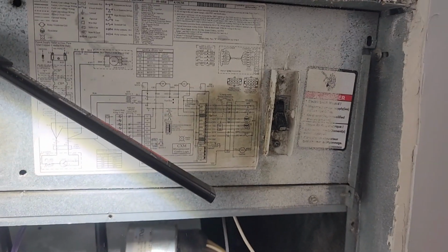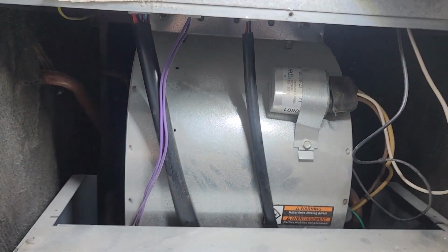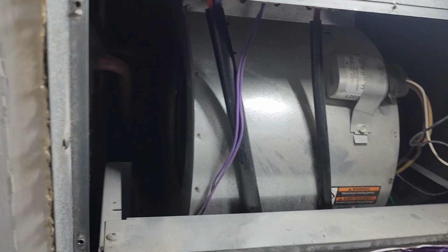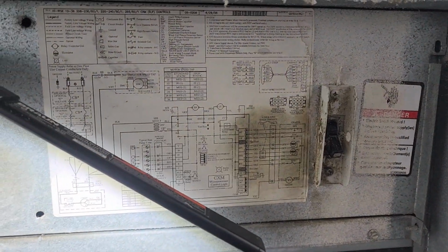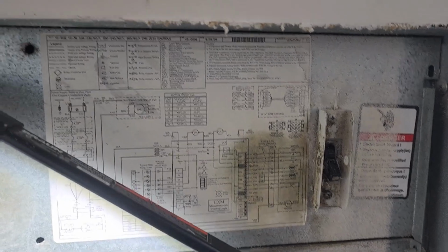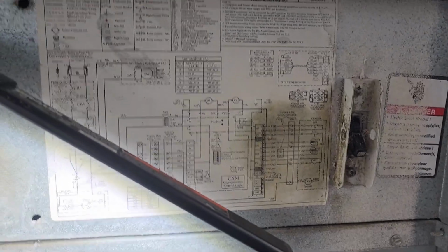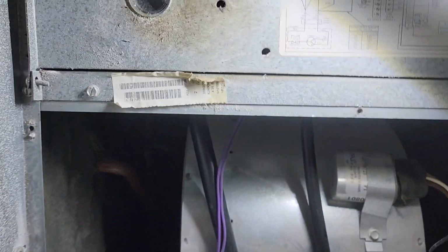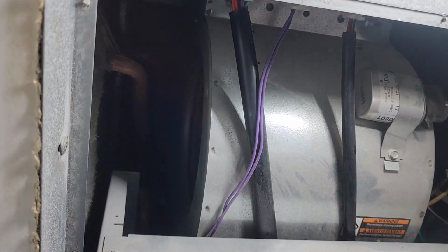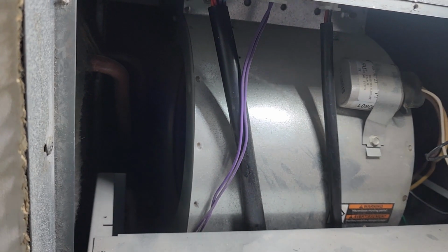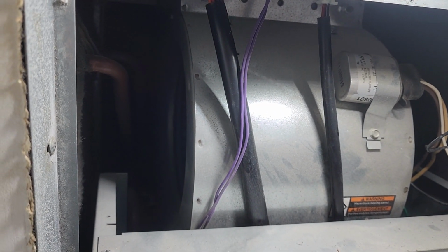So I turned this switch off, and by the way, if you're not 100% sure about where your electrical supply is, I know just from looking at everything here that it is all on the right side of this top area for the high voltage supply that would be controlled by this switch. But if you're not sure, by all means, go ahead, turn off the breaker in your main box, because better safe than sorry.